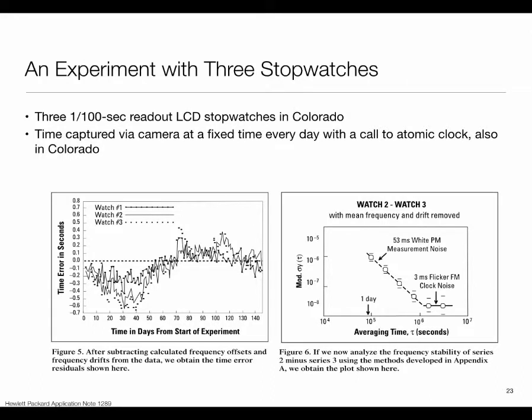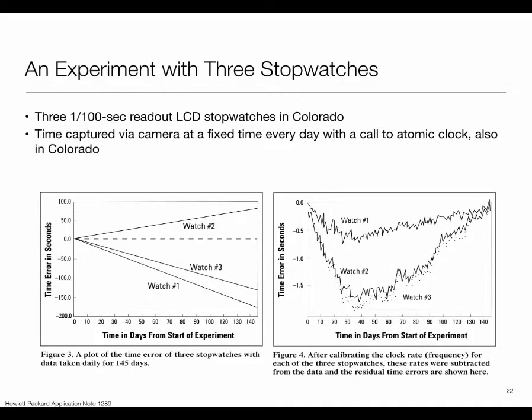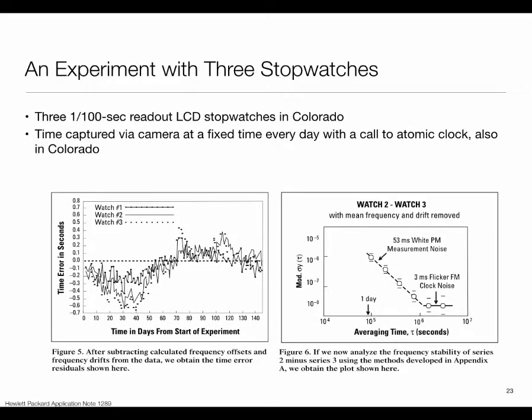So going back, they estimate from these things what the drift in the frequency was. They compensate for it, and once you compensate for it, you can begin to see that I can make otherwise flakier clocks more stable. By compensating for this, all these clocks are meandering around the 0 point. I still cannot cancel everything out, because canceling everything out would mean I know the precise changes in the frequency. So essentially we are fitting some low order polynomial, let's say piecewise linear